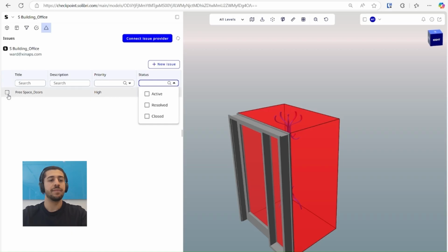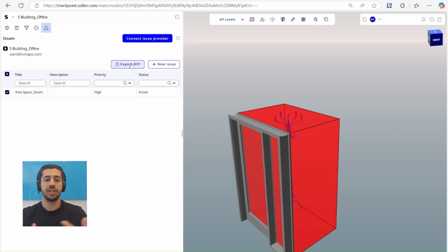And also we can see, we can have an option to export to BCF, or if we have more than one issue, we can export to BCF zip file. And this is how we can fix this issue basically now on ArchiCAD. I can export this to BCF. I can send it over to Pelen, and they can view the issue and fix it over there.